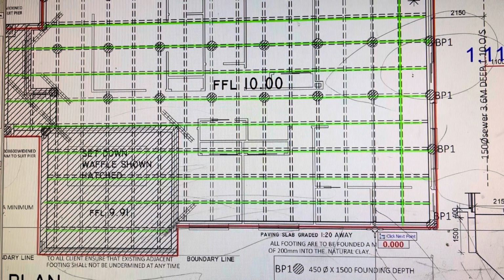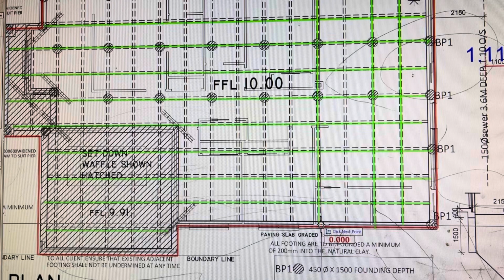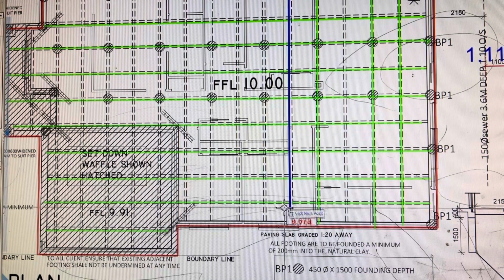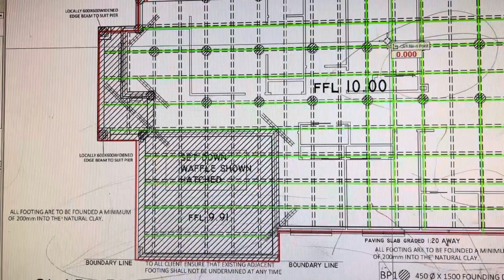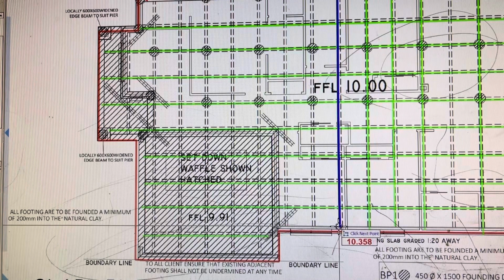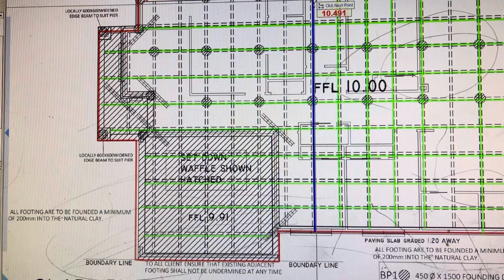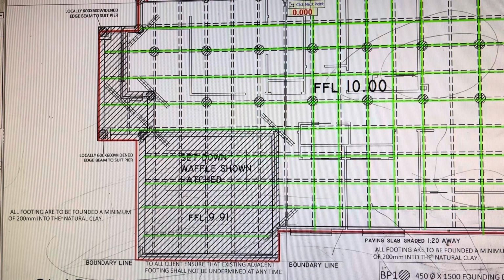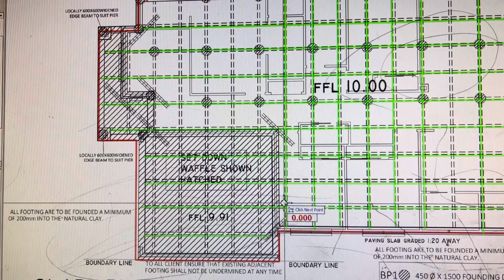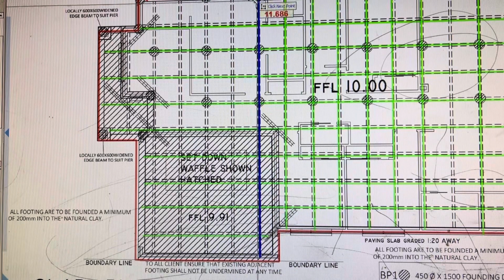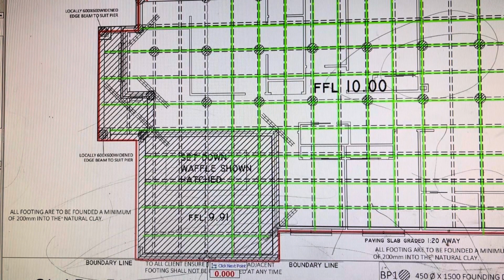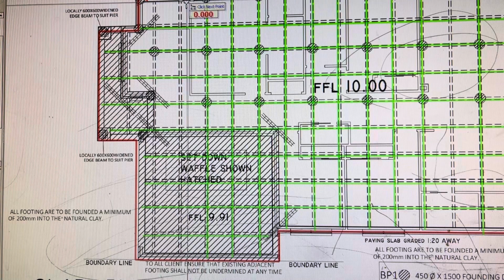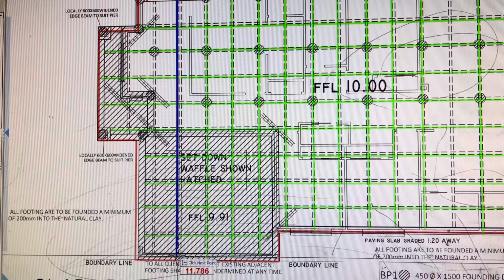So estimating is very important, guys. Quantity surveying is the first step. If you get the quantities right and you apply a correct rate analysis, then you'll arrive at a right construction figure, which is called estimate, and then you can put some contingency and on top your net margin, because estimating and quantity surveying can make or break a company. If you estimate wrong, if you have the take-off quantities wrong, then your estimate will be wrong, your tender figure will be wrong, and you are signing a contract on your life with the client. Once you sign, you have to honor.